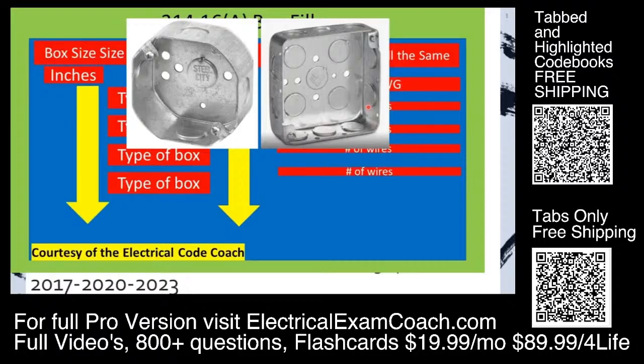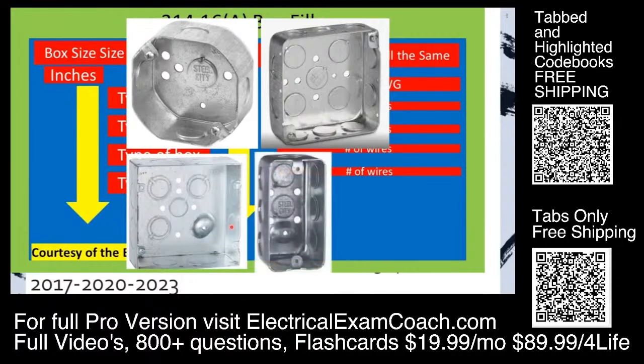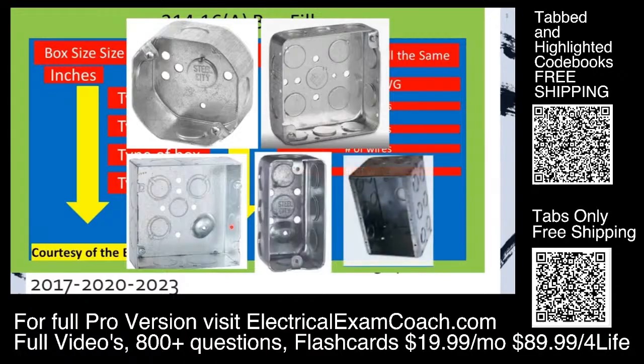There are 3 different depths. The next 3 lines you'll notice say square as well, but its dimensions are a little bit different. It says 4 11/16 by 4 11/16 by whatever the depth is. Down below there start your device boxes in all different shapes and sizes. Finally, we come to our masonry boxes. Listed below there, you're going to see different types of raised covers, which also give you a little bit more cubic inch volume inside of your box.